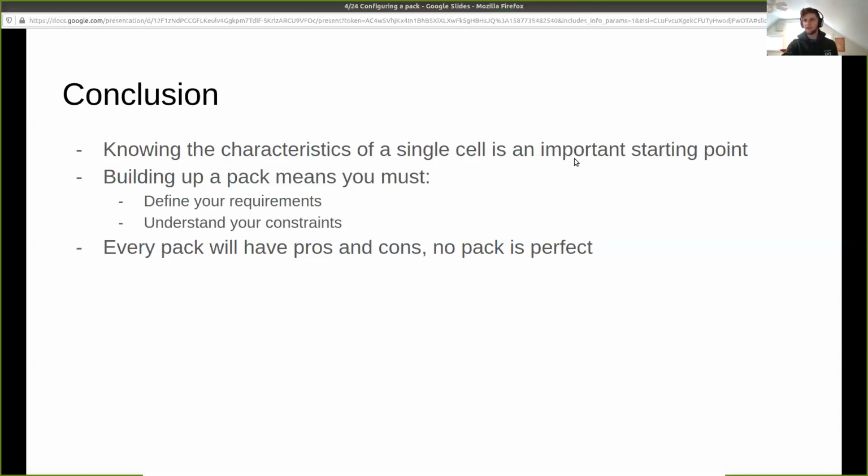So the motor controller, you'll send it a signal and it'll supply a certain amount of amps for output, and that'll determine your speed, or is it voltage regulated for speed? So the motor controller gets a torque request from the pedal, and depending on the speed that the transmission is running at, it converts the amount of torque that you're asking for to a certain amount of power needed. And that maps back to the same equation we just talked about, power as voltage times current. So whatever voltage your battery pack is at, it draws the right amount of current to get the right amount of power to deliver the right amount of torque. Gotcha.